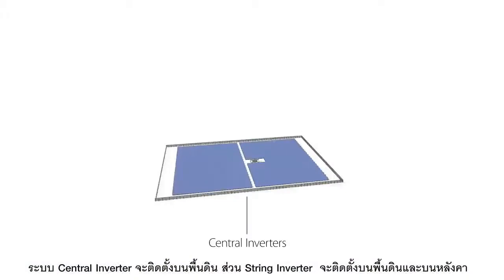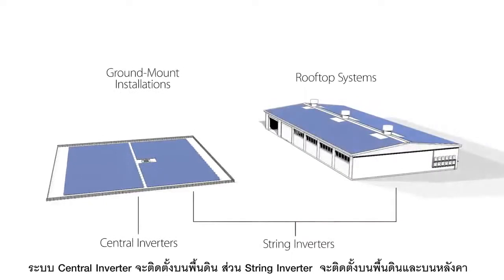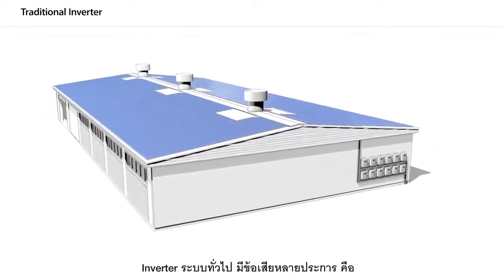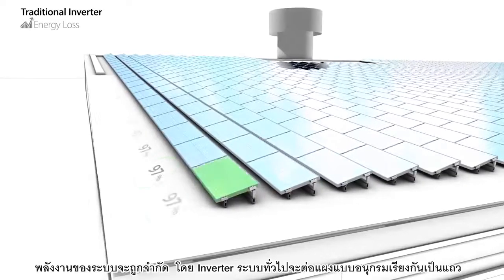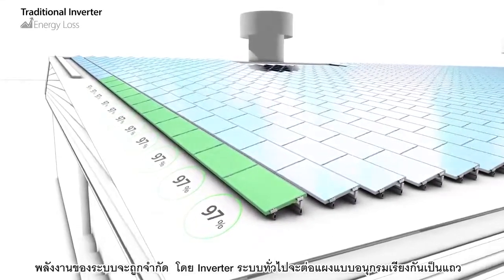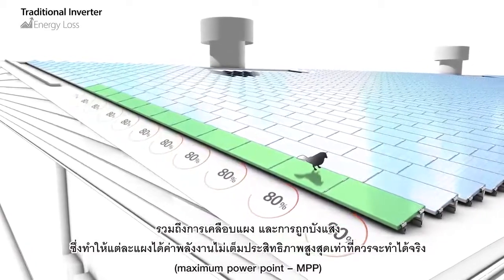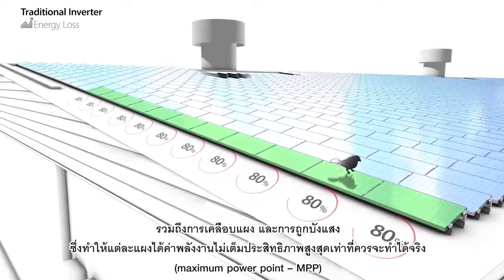While central inverters are typically used in ground mount installations, string inverters are used in both ground mount and rooftop systems. Although traditional topology using string inverters is still used in the majority of large-scale installations, it suffers from a number of significant drawbacks. First, the system power output is limited. In traditional systems, panels are wired in a series as a string. Each panel has its own power production profile. This is a function of its manufacturing variables, installation parameters, and shading patterns. This means that panels don't usually work at their maximum power point.